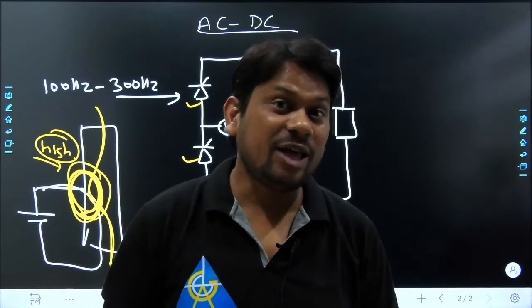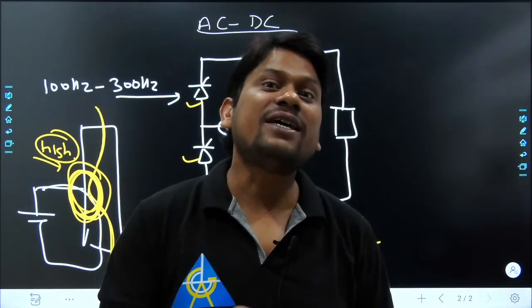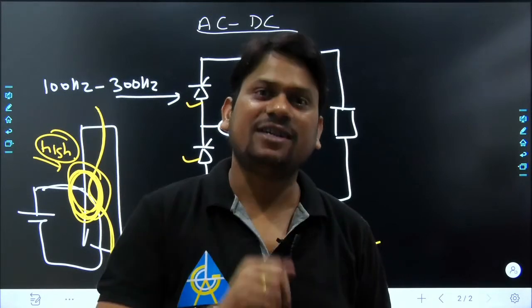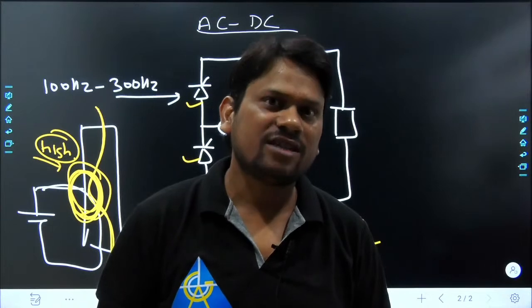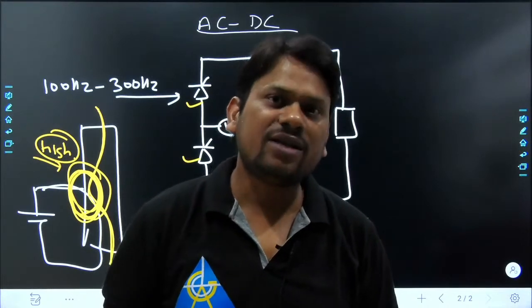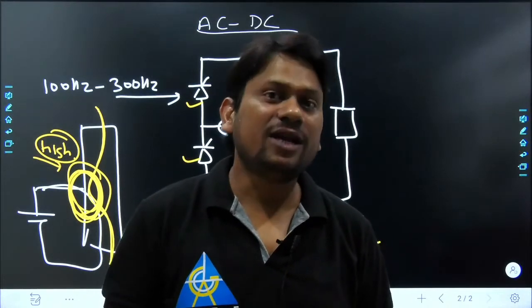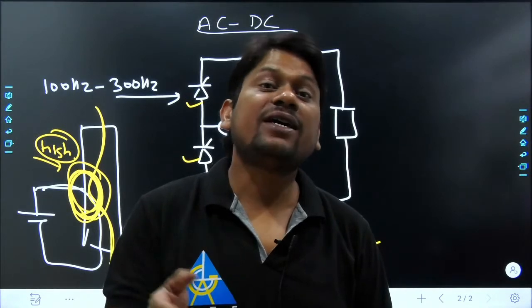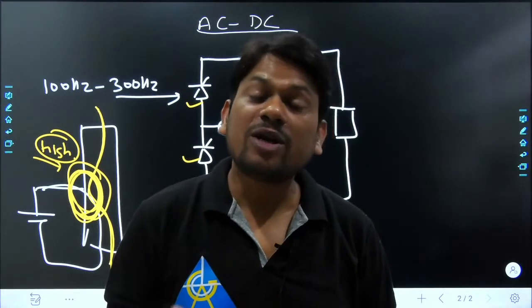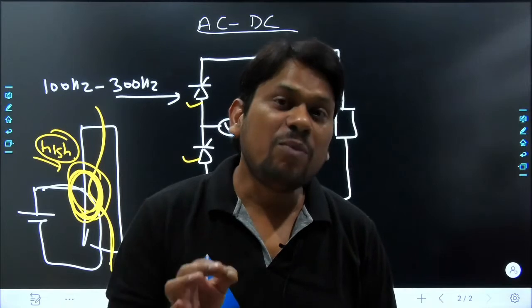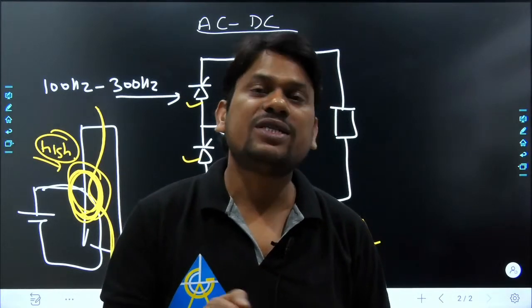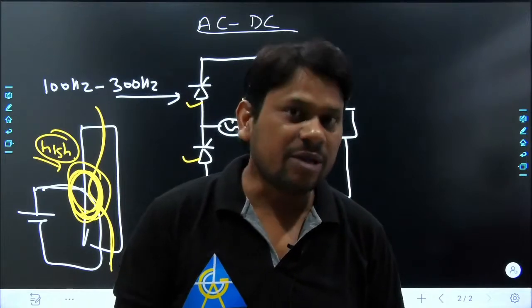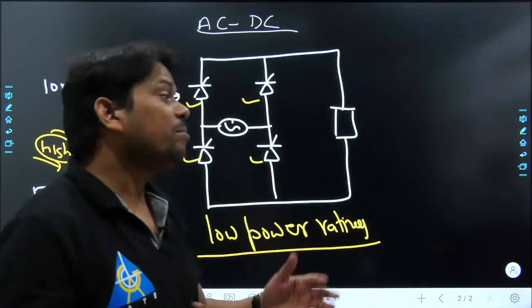Because if we want to control the cycle at any instant, we will not trigger our devices before our requirement, and in this period, our devices will behave like an open circuit. So our entire supply voltage will be blocked by those devices, whatever we use to design our converter. So here we have many choices.